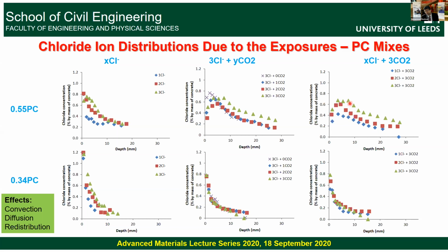And when you go to another exposure combination, the chloride content maximum has been shifted again interior to the concrete. So if we predict the corrosion caused by chlorides using this model, that cannot be applied to these two combinations. Now, here we are seeing a really unusual pattern.